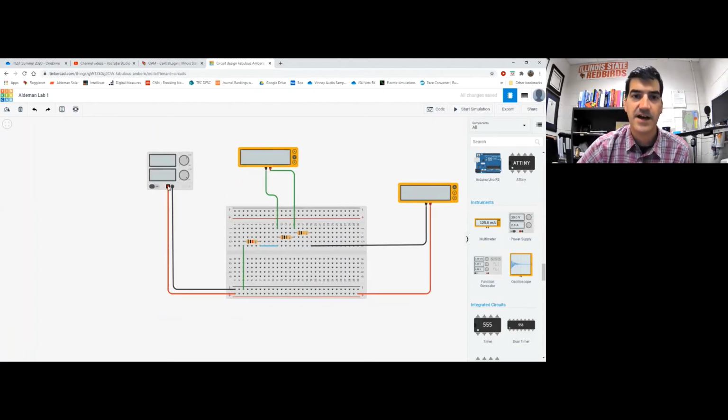Positive side of the voltage source, so the current comes out here through the red wire, through this strip to this meter that's measuring current, and then out this side to this part of the breadboard right here. It'll go through this resistor, then it'll go through this resistor, and we also have a multimeter measuring voltage drop across this resistor from here to here.